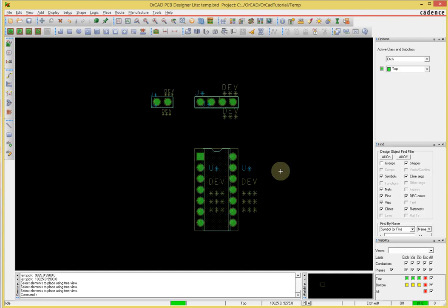The footprint question must be known, must be decided, must be finalized. You just cannot go through a complete design and then find out that your footprints are wrong. This is a complete disaster. You need to know what footprints you're going to use, and you need to be 100% certain it will do the job for your particular needs before you do anything further. I haven't started layout. All I'm doing is evaluating the suitability of these footprints for my parts. That is a very important message, and it's the most important part before you finish the schematic design in OrCAD and move on to create the netlist and move on to the PCB layout.